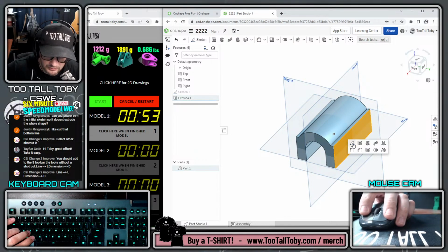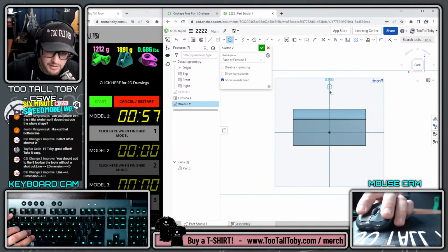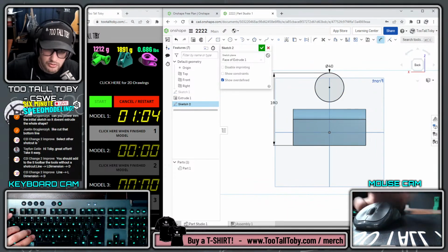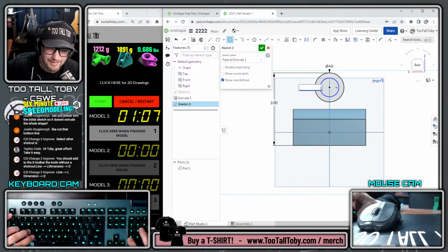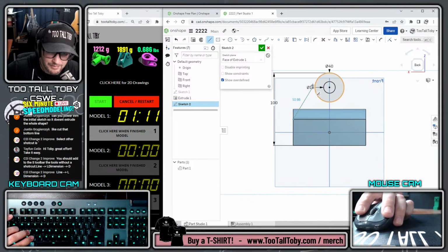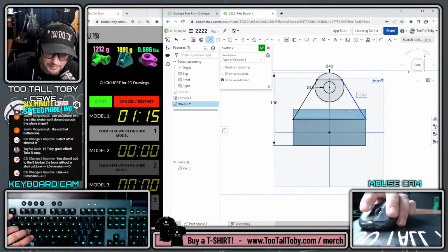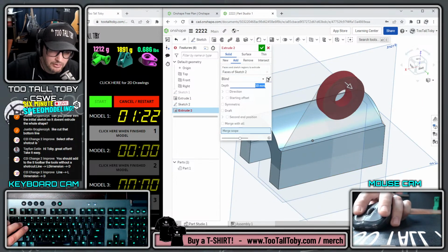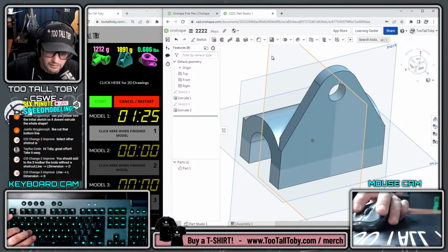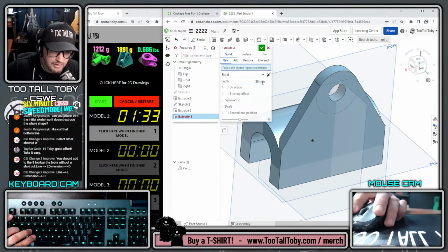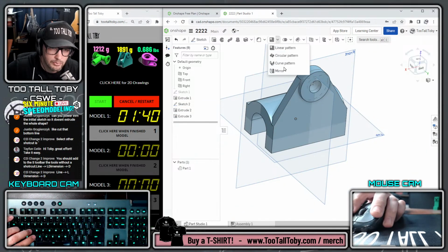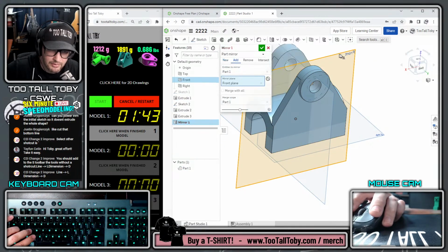We'll go to this face, begin a sketch, get normal 2, and this is going to be a circle with diameter 40 and a distance from the base at 100. And this time I'm going to try to remember to put that other circle in there, make that 16, and we'll create a line here. Deviating a little from the plan on the fly, never a good idea, I know, but I wonder if this will help us. And we're going to go extrude, and that's going to get extruded to a depth of 10, and it's going to be these guys. Okay, and then we'll show that sketch and extrude once again as a solid here, 5, and it's going to be this and this. I'd say that worked out pretty good, and we're going to do a mirror. And it's going to be all of this about this plane.